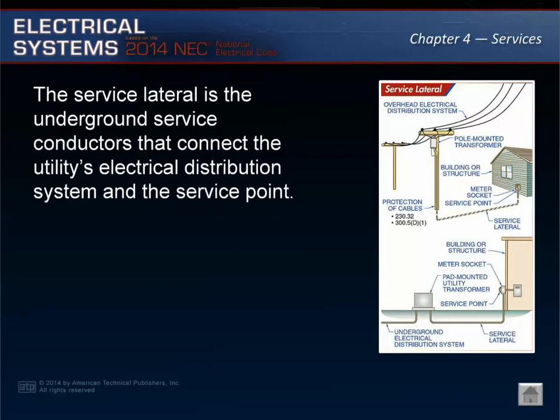The service lateral is the underground service conductors that connect the utility's electrical distribution system and the service point. The utility supply system can originate from a pad-mounted transformer or an overhead supply system with the conductors emerging from the ground and continuing up the pole.